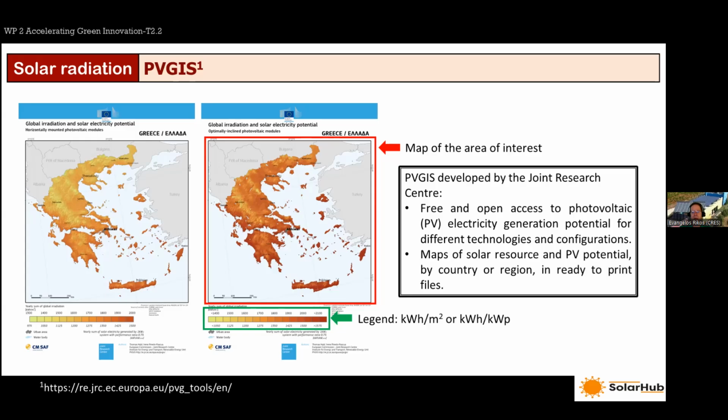However, because I presented you all the previous mathematical models, one could wonder why or where these are needed. If you want to, for example, design a system that is optimized, and you don't want to generate any shading between rows of solar panels on each other, you have to place them at specific distances.